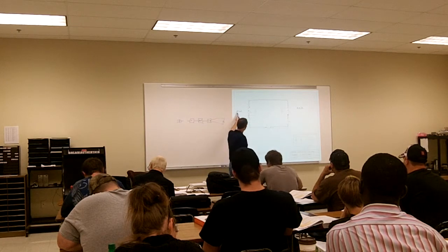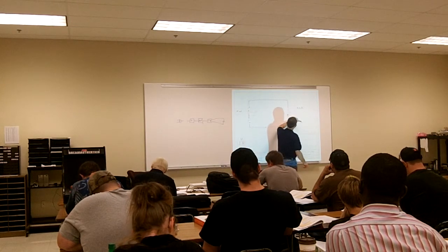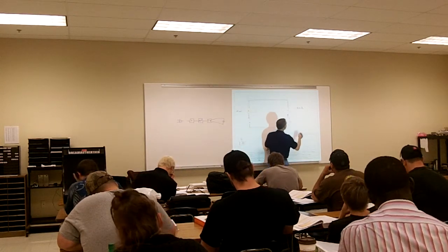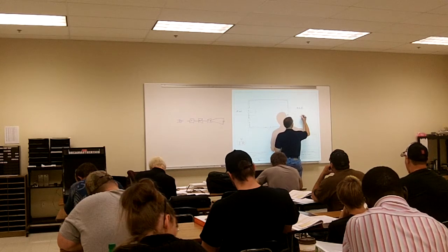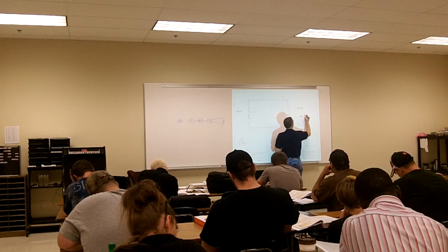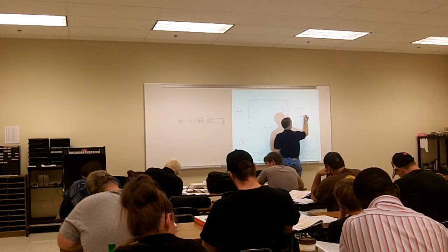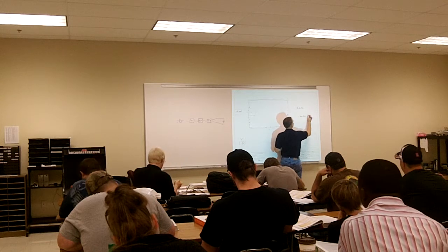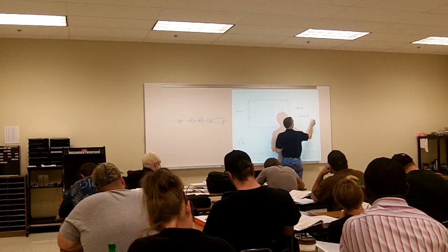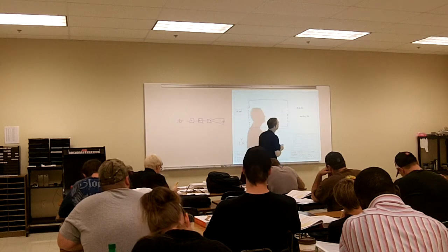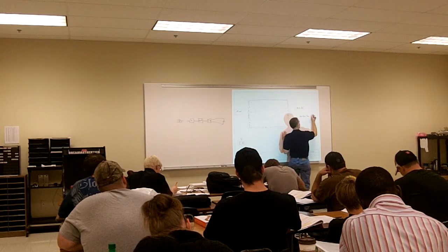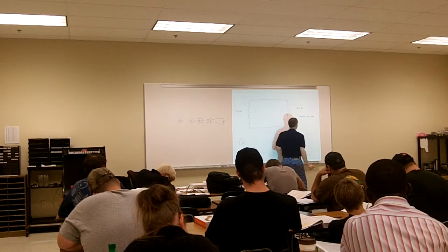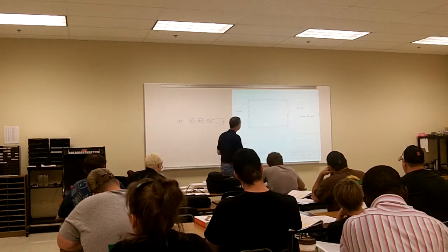So we know that we have 24 volts, we have 120 ohms, and do we know what the color code is? Brown, red, black, gold. Yeah. So it should be brown, red. And what's the fourth band? Gold. It's going to be plus or minus what tolerance? 5%. Alright.